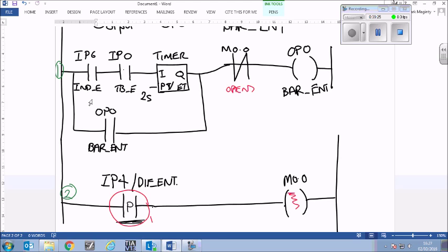So a normally open contact like this OP0 here gives an output from itself the whole time it finds a 1. This one provides an output the whole time when it finds a 0. And if you use the other version, the N, negative edge, it would only be active for a very, very short time, milliseconds. So once something goes from off to on, that activates very quickly, which would operate our M0.0 in this case.